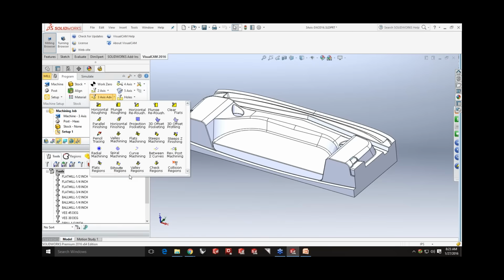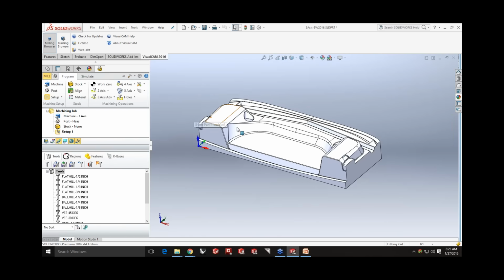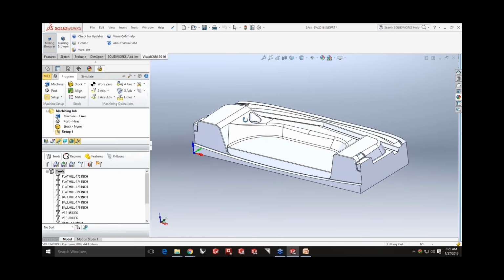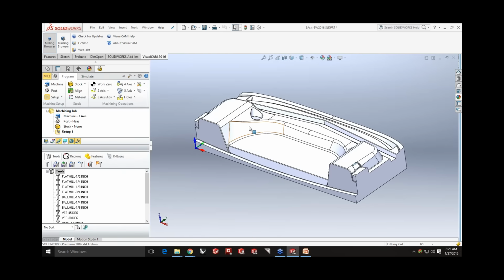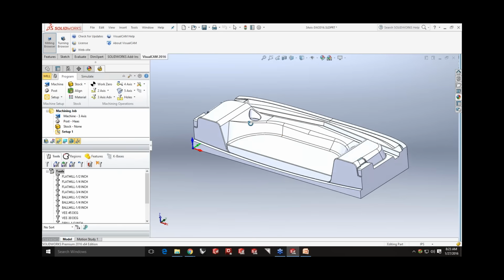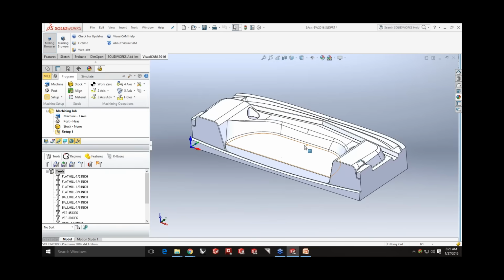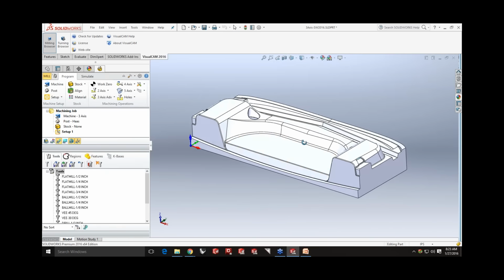With our standard and expert configurations, roughing, parallel finishing, horizontal finishing, radial and spiral machining are included in addition to 2.5-axis methods. Now, a part that typically has sculpted surfaces, complex 3D surfaces, fillets, radiuses, and drafts on the part would be ideal for programming as a 3-axis toolpath. Now the workflow is very similar to how we programmed our 2-axis toolpaths.